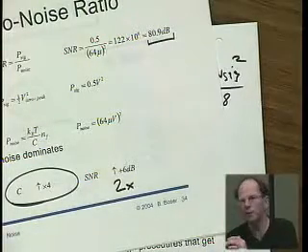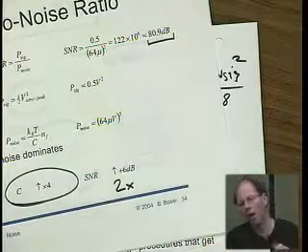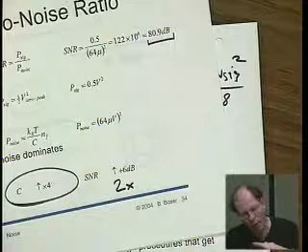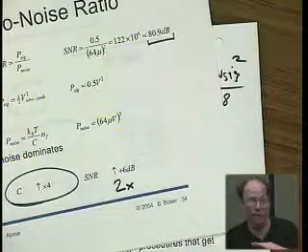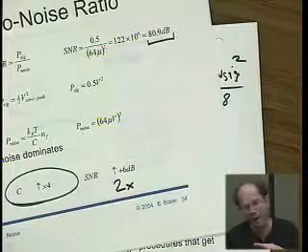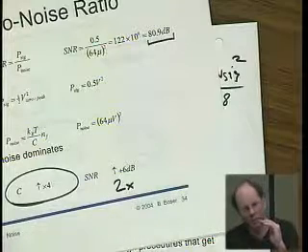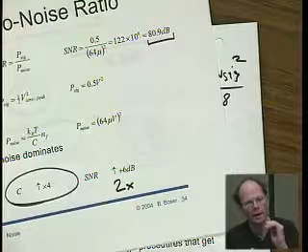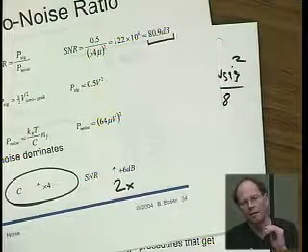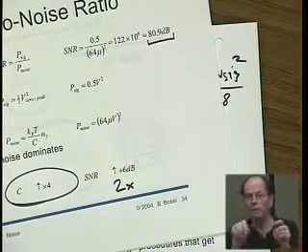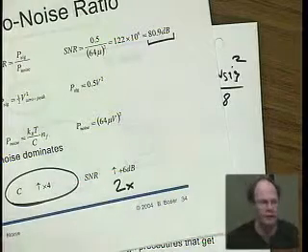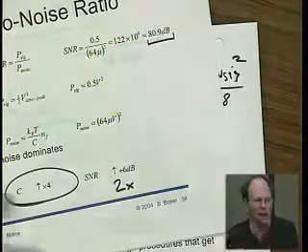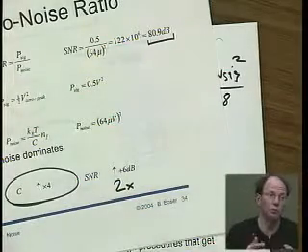So consequently, if we want our LSB to be down by a factor of 2 in order to have an extra bit in our A to D converter, then we're talking about the voltage ratio improving by a factor of 2. Now 20 times log 10 of 2, of course, is 6 dB, right? But that means that the power ratio, the volt square ratio, had to change by a factor of 2 squared, or 4.